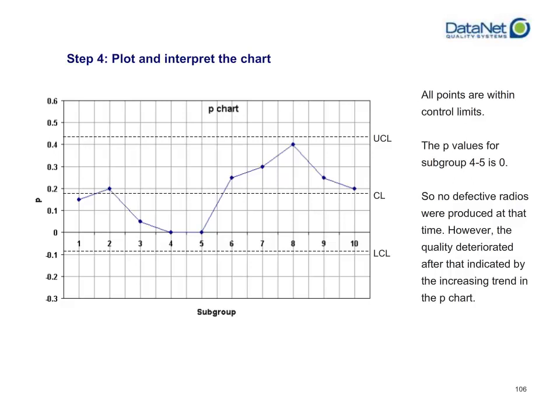Can't know for sure. Everything is within historical norms, so there's nothing in this data that would indicate that you need to adjust your process. Even though you started seeing at subgroup number 8 that you're getting really close to your control limit, it is actually within the control limits. You would not recommend that you try to tamper or intervene based on this information. It isn't to say that you probably don't want to figure out why the quality changed over time, but as far as an alarm to immediately act and change something, we can't gather that from just the information we have here.